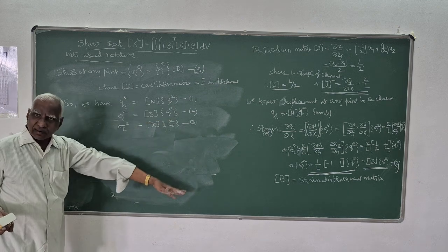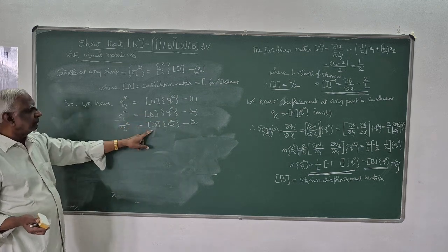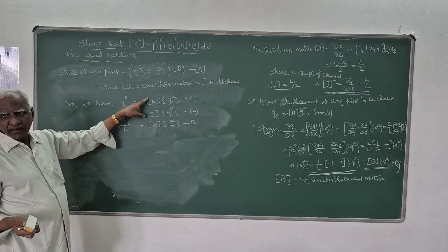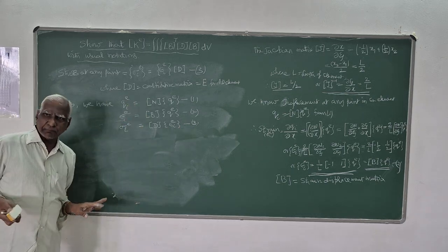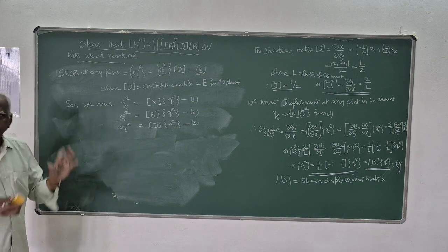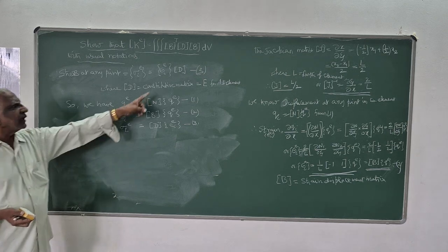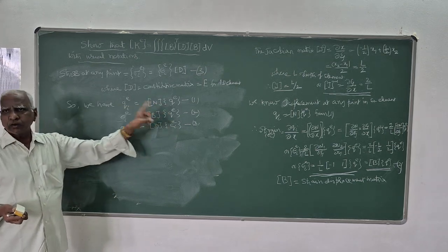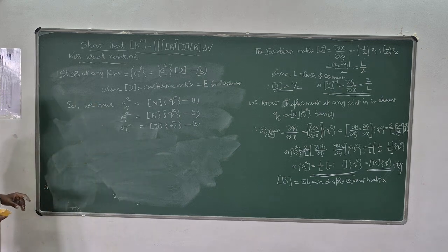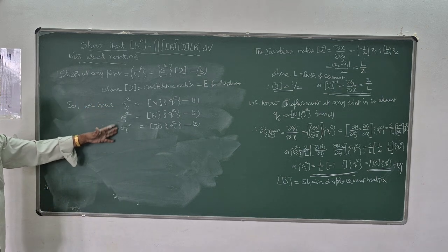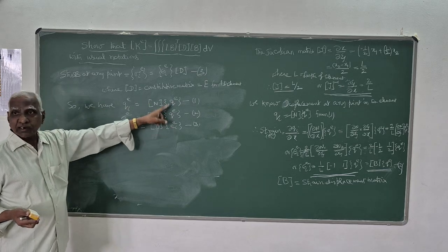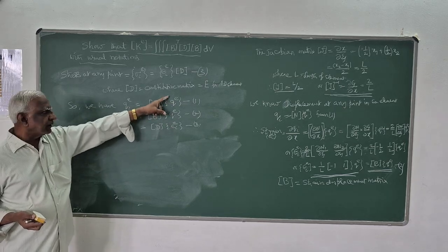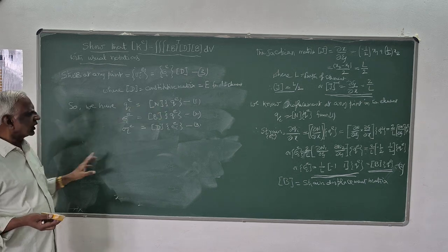Usual notations are this, that is D, B, N. N is the shape function, B is the strain displacement matrix, D is the constitutive matrix, and of course Q is the nodal displacement vector. And these are the unknowns which you can get. All are functions of nodal displacement vector. Mind it. That is the one which you have to do.